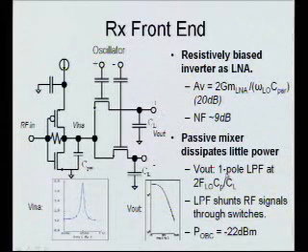So that was just, we've already talked about this. The wideband compression point of this thing was about -22 dBm. And as we'll see in later results, this turns out to be really conservative, because models of passive mixers don't work very well from a linearity perspective. Just the way that FETs are usually modeled, it always assumes there's a drain and a source. In a completely passive switch, the drain and source are arbitrary. The way the model handles it, it takes whichever one is slightly larger and calls that the drain, and the other one the source. So if you're swinging signals across it, once an LO cycle it switches what's drain and what's source back and forth, and there's some discontinuity, and it makes things nonlinear. But it turned out to be a very conservative simulation.